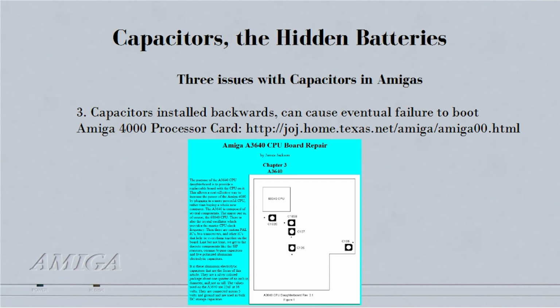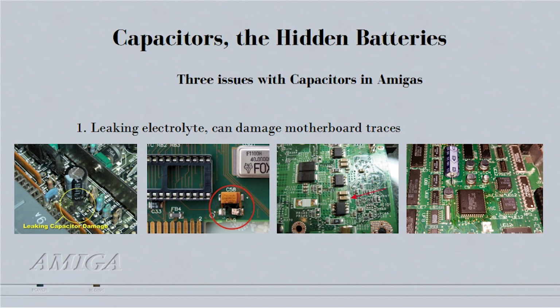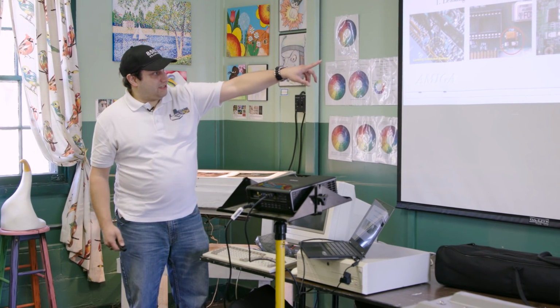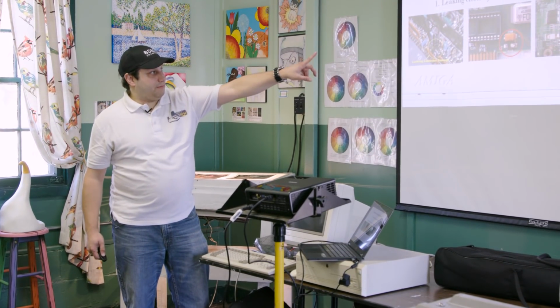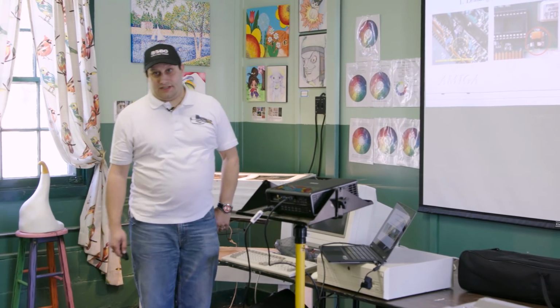So this is some pictures, leaked capacitors. This is the second thing I do after removing the battery: I look around on the motherboard for black or brown stuff underneath these barrels, near these orange things. And with the surface mount, you got the little silver guys. Sometimes what you'll see is this black, oily stuff. And you can see it's all around that chip, that black, oily stuff.